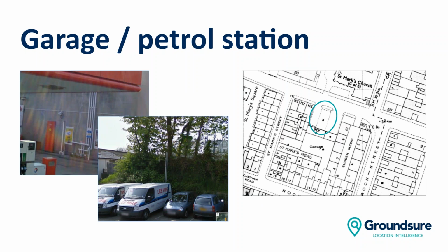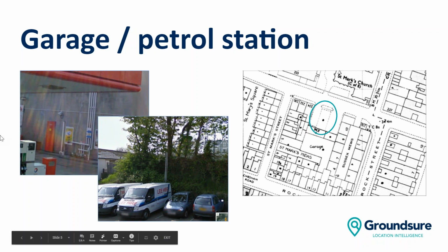Another obvious sign, of course, as I mentioned, would be the vent pipes. So perhaps when converted to use like a car wash, the interceptors and the vent pipes are usually left in situ, so it's a nice clear indicator when undertaking a site investigation as well. And for those that aren't familiar, vent pipes often appear as these sort of structures, perhaps standing independently, and often will be near a car park, because naturally, with the offset fills, you need to get a sort of tanker up near.